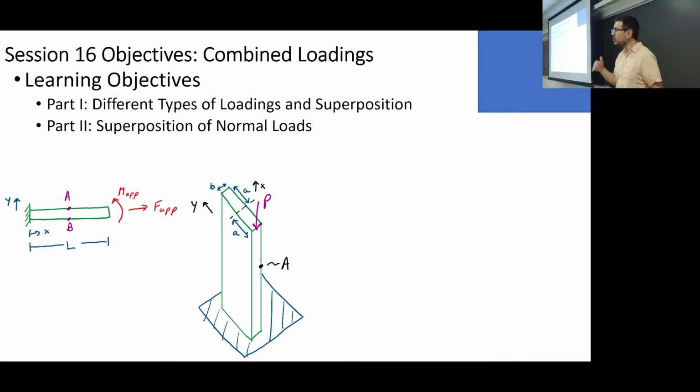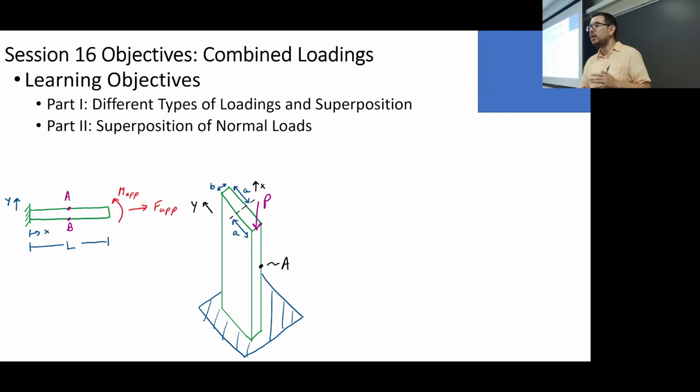We don't talk about buckling in this class. A lot of times in mechanics and materials I do, but we don't. But buckling, yes, is a big problem that we'll quantify, at least for columns, in the next class in DMC. But it's complicated in other structures, with pressure vessels for example. That's where you can use finite element, or you could look in a textbook and have analytical solutions.